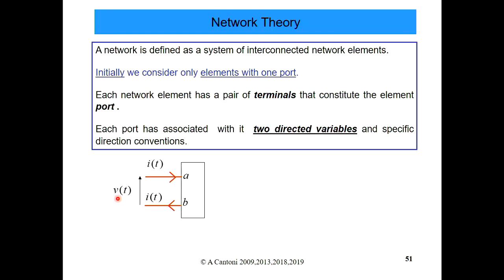It's called the, from last year? Rise variable. What else? Potential difference, right? So it's potential difference, and it's measured in volts. It's not specifically the voltage. The voltage could be other things, but in circuit theory, we deal with potential difference only. We'll see in the second half things that also generate a voltage, but they're not potential difference, and they don't belong to circuit theory. In circuit theory, it's all about potential difference.